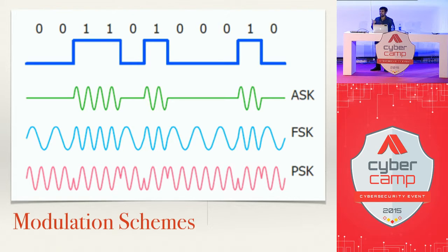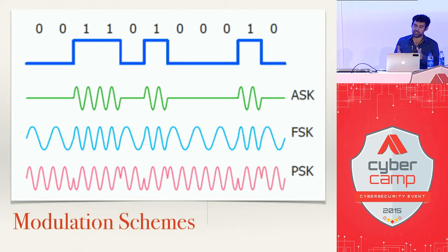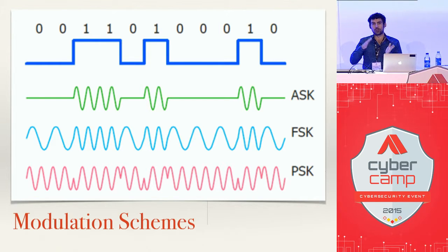Frequency shift keying, or FSK, is another one. If you've ever heard of FM radio or listen to FM radio in your car, FM is frequency modulation. FSK is a type of frequency modulation. It's where you're shifting between two frequencies to basically represent ones or zeros. And there are different types of FSK, where you can have 4-FSK, where you can actually represent 0 0, 0 1, 1 0, 1 1.